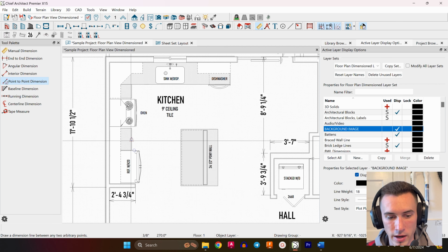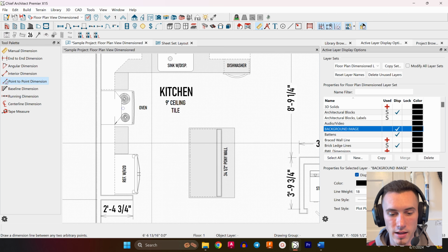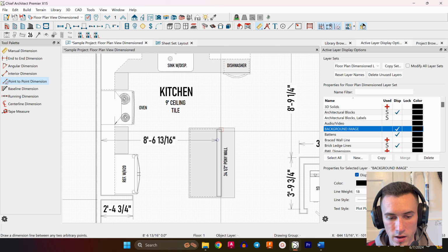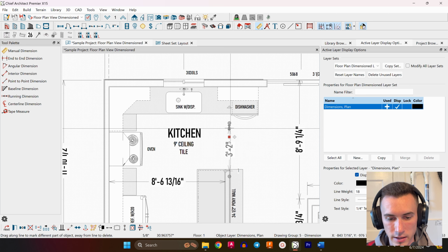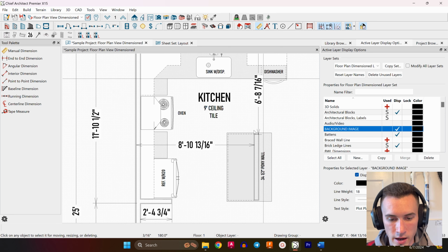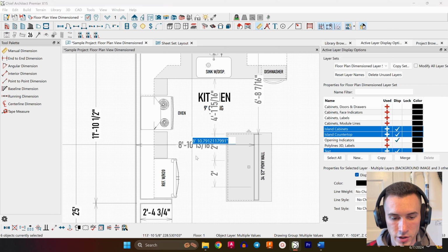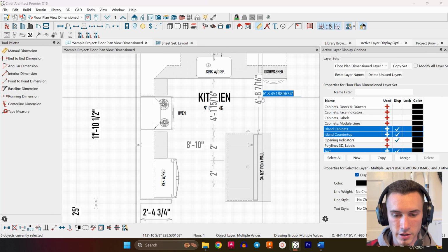Now we'll go point to point off of the framing to our cabinets. All right, now we're going to define the island, and because there's a wall here, we're just going to define the wall. We're going to go framing to framing, and then we'll go framing here, and extend this over to the framing from the outside. And then these are weird dimensions. We'll go ahead and grab this whole thing and adjust to 8'10" and adjust this to 6'8".